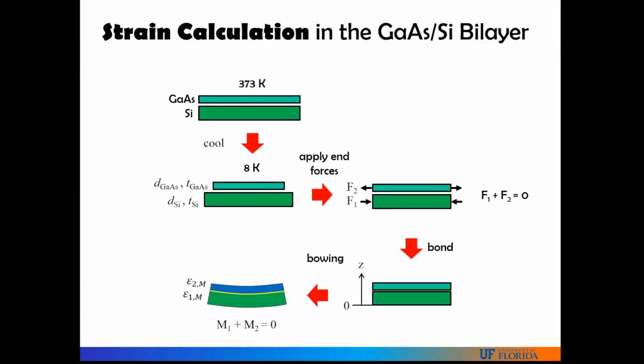So there's actually a paper that does an analytical treatment of a multi-layer, composite system. The way the model works is you take it customized to our particular bilayer sample. If the two samples start by having the same dimensions, you cool them down, and due to different rates of contraction, the gallium arsenide contracts more than the silicon.